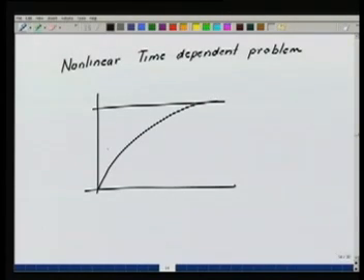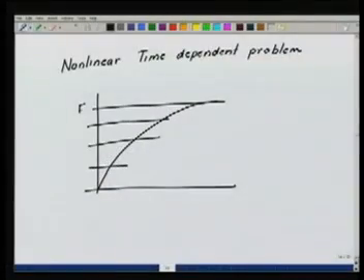Okay, so let's say this is my f. So it's better, in fact I could have done it for the problem that we had been discussing till now in the Newton-Raphson regime, that I break the loads into small steps, delta f1, delta f2, delta f3, and so on. Okay, and I solve the problem in steps for these incremental loads.